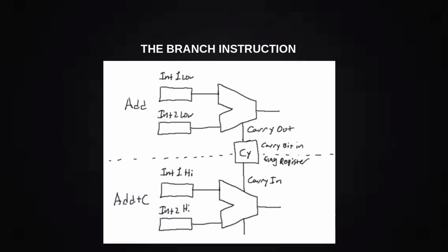Well, storing something like the carry flag allows you to use the carry bit in an add plus carry instruction, which allows you to add integers wider than your register width together. But it also allows you to store the flag's current state and restore it later should you need to. That sort of thing really is only useful if you're implementing interrupt handling and/or giving your CPU a protected mode, which is outside of the scope of this video.